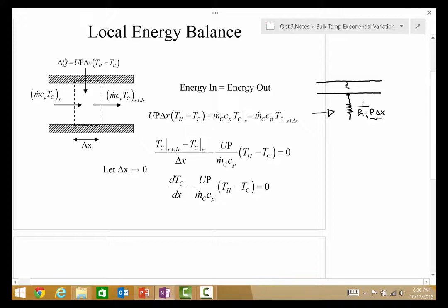And in general, we have some sort of conduction resistance within the pipe, and then you might have, for example, some sort of heat transfer coefficient, or said differently, a resistance on the other side of this problem. We might denote that by HO, call this PO delta X, and so we'll call this PI. So the parameters are different. PO would be 2 pi RO, whereas PI is 2 pi R sub I.